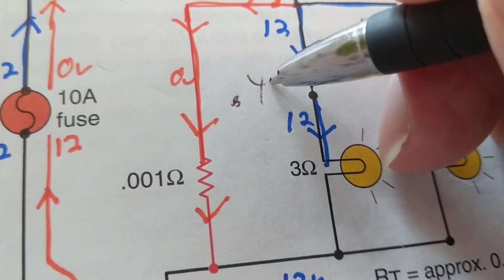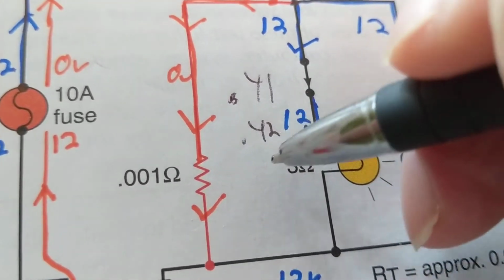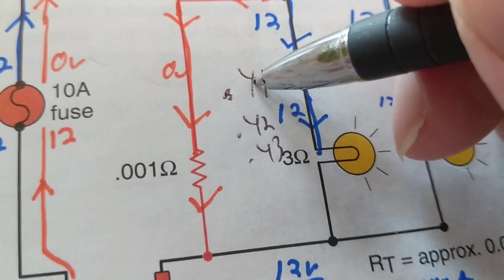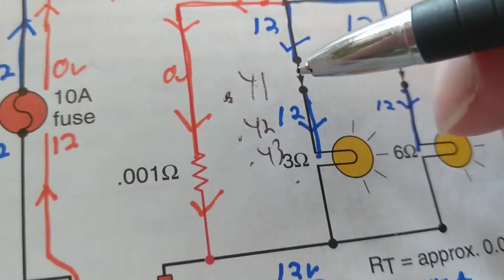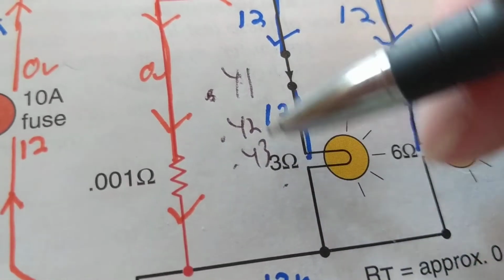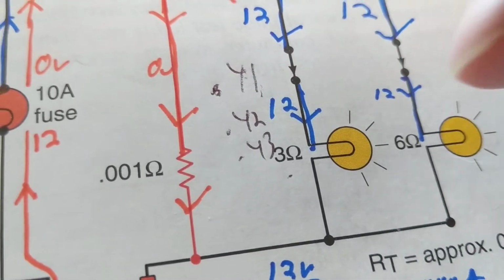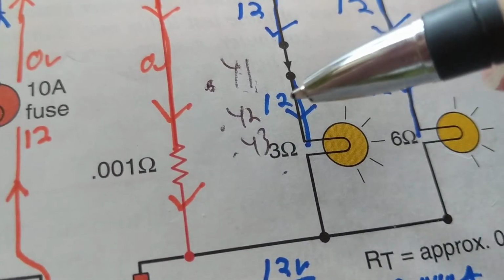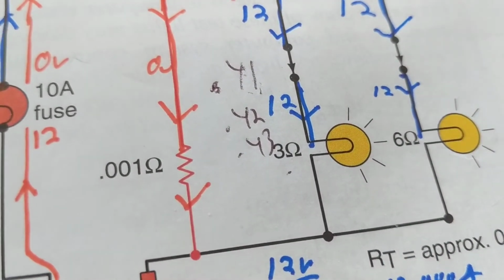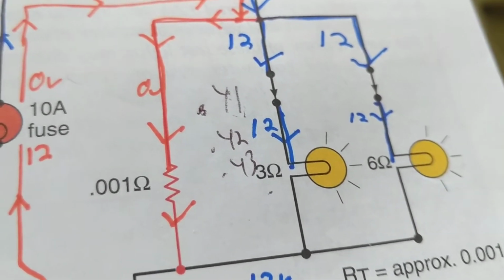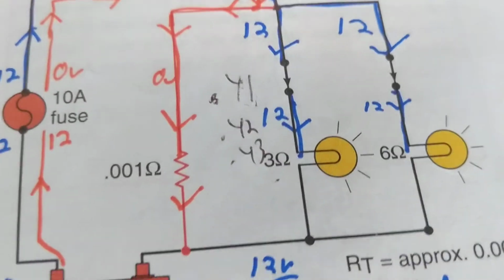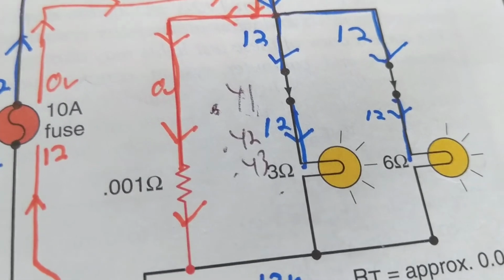The computer sees 0.4. 0.41 makes a difference. 0.42 makes a difference. 0.43 makes a difference. So you cannot just adjust it. If I need 0.4, I can't adjust it to 0.5. No. The computer has these parameters in its program from the engineers. Every single thing has a different air-fuel ratio for the computer to look at. Again, a Corolla has a different one. Make and model, they're different. Check the manual. I'm going off topic, but that's what I was asked. Make sure, otherwise you will have hesitation problems if you don't adjust your TPS sensor correctly.